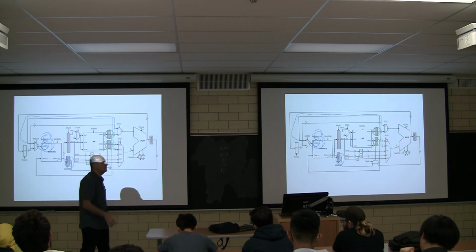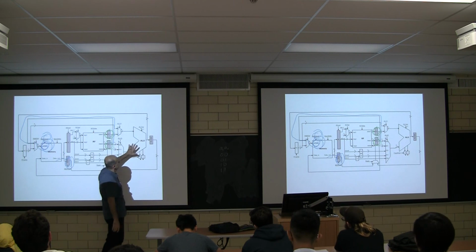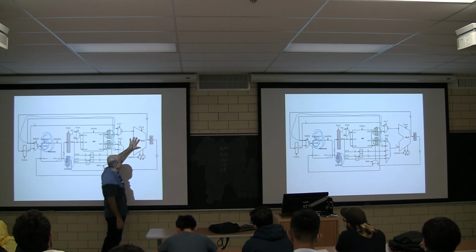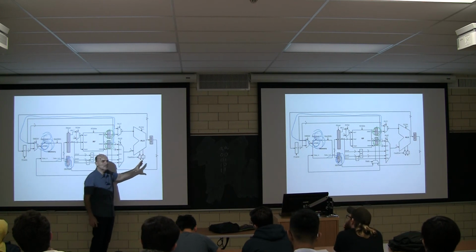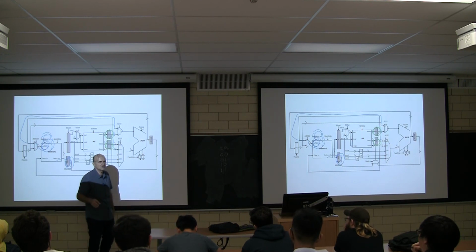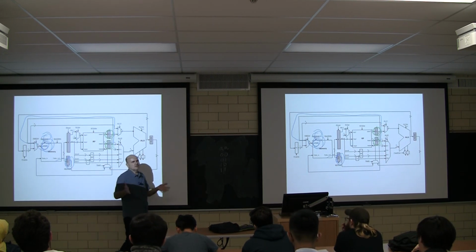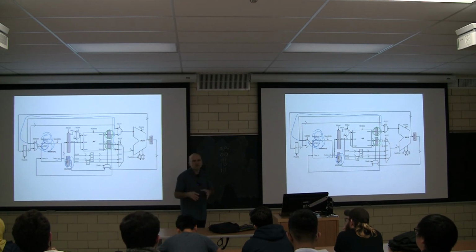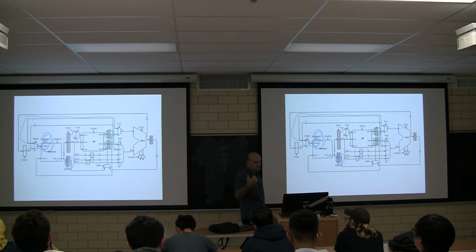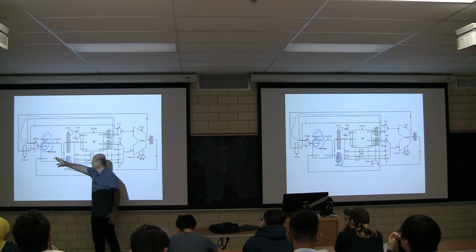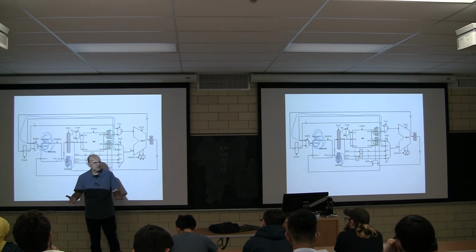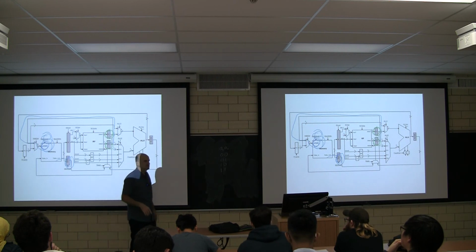So what I'm trying to say here is the following. You could have said in one clock cycle, calculate a new result from the ALU out and directly write it back to the register file. But underlying here is the assumption that I will make your clock cycle almost twice as long. And this is a fair assumption for most circuits out there. How do I know that? I mean, you have to design the circuit to see what it is, but take my word for it, this is usually what happens. Okay, so memory data register is a staging register that you use because this block takes quite a bit of time. So if you want to go directly into the register file, it will make your clock cycle twice as big. Fair enough?